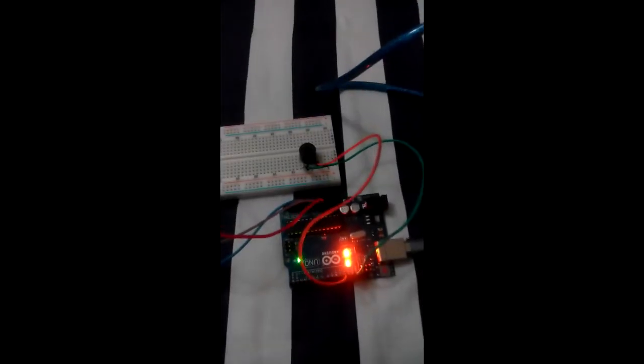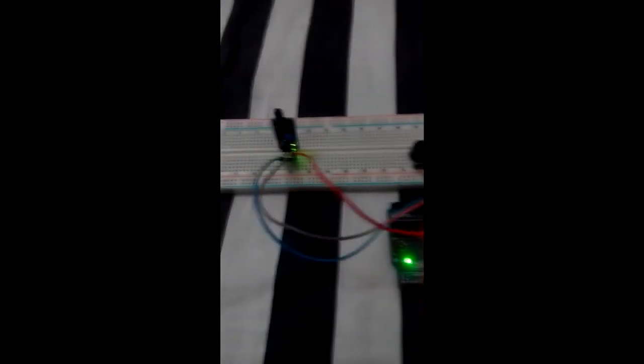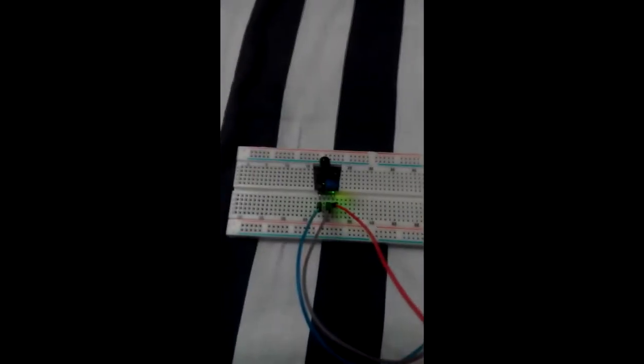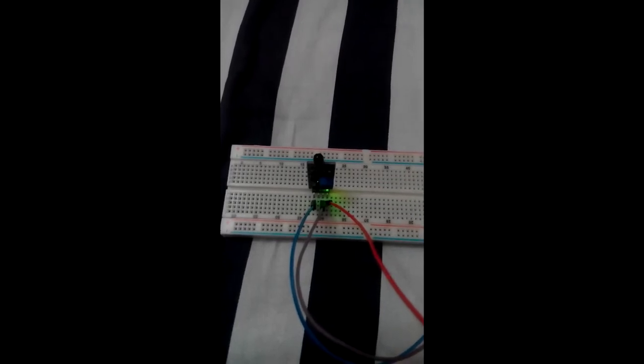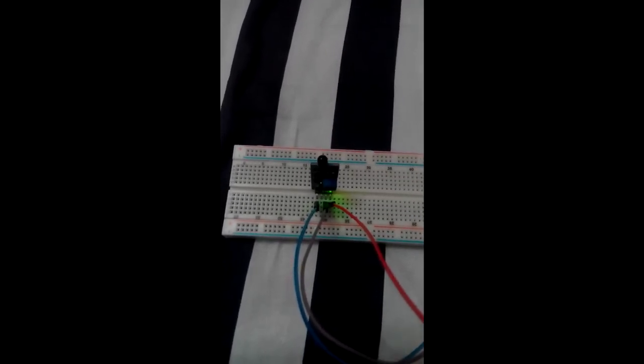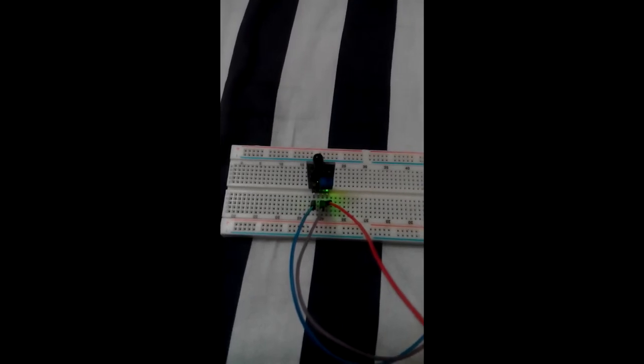Here we can see that two wires, orange and green, go to the buzzer. The orange pin is for Arduino pin 12, and green is the ground. The red wire is the voltage, which is the VCC, ash goes to the ground, and blue is the input wire for analog A0.